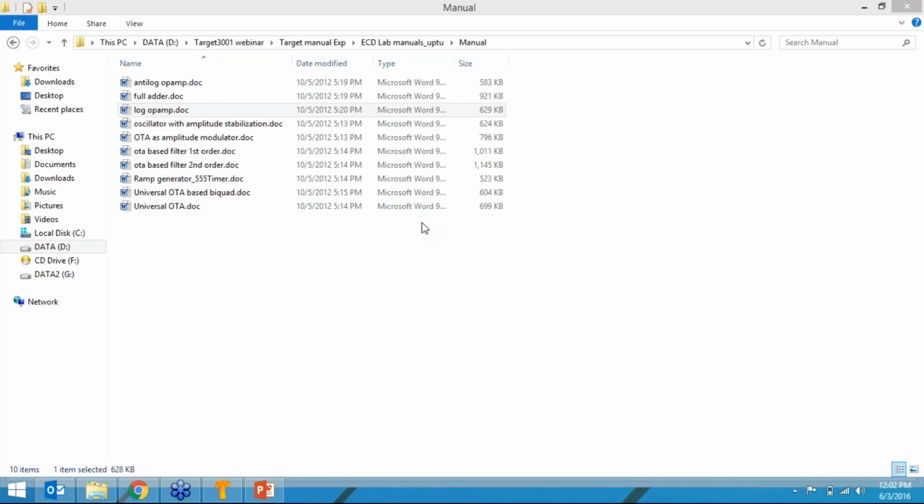There is one question: is a connector compulsory? A connector is not compulsory if you want to simulate this circuit. But if you want to generate this layout, you have to connect the connector, because you will not get the source in the layout if you connect directly.